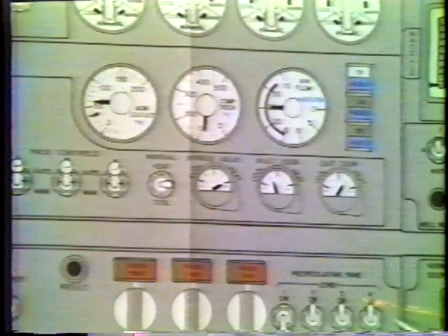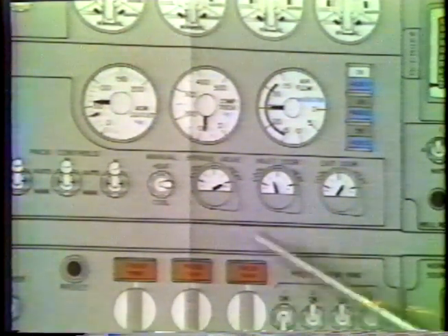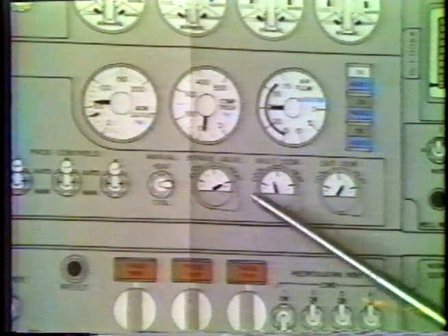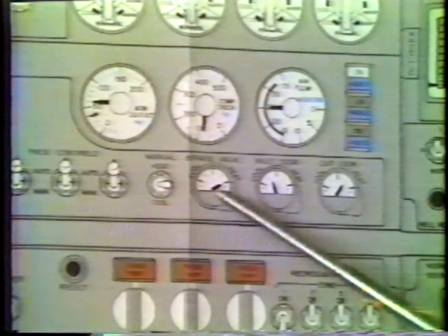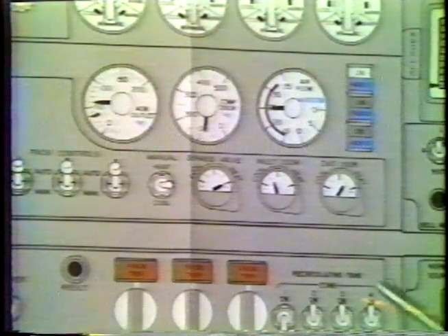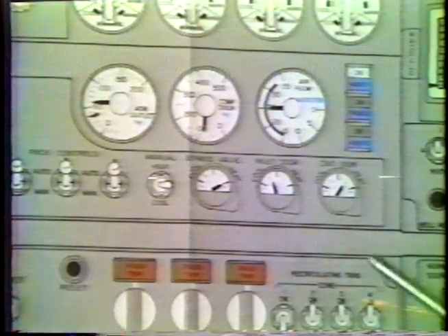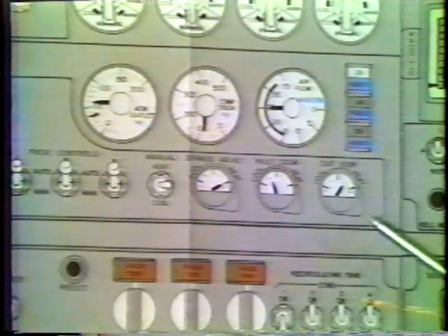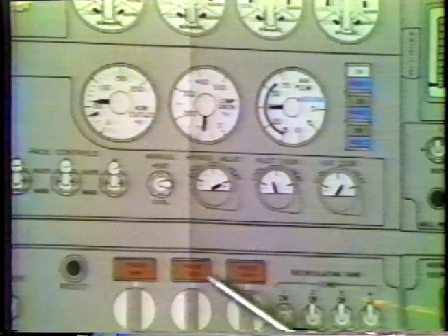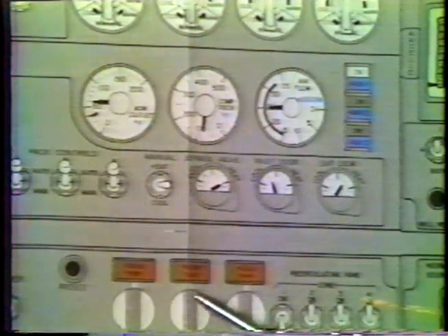The disadvantage of this is like manual pressurization. Every time there's a speed change or an altitude change, the bypass valve has to be repositioned and requires quite a bit of attention. Again, the airplane will very nicely do the job on 2 packs, and if you have to operate in manual, it may be better to just leave that pack off.